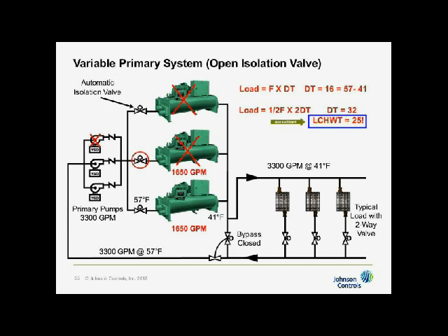So 25 degrees, of course, is never going to be reached because the low water temperature cutout is going to kick out 4 degrees below set point standard. So my 40 degrees, when it gets to 36, off she goes, and you can imagine what a nuisance that is when you have this chiller running, you just want to add the second one, and this one trips off on you. It all happens because this valve that's here is 2-position, it just opens in 10 or 15 seconds.